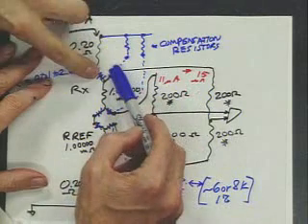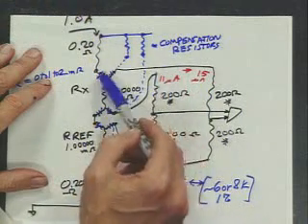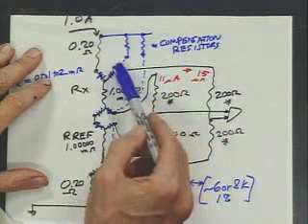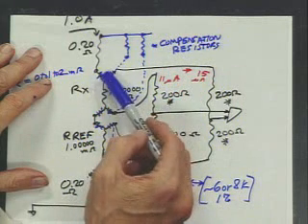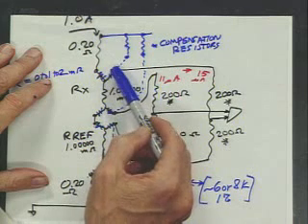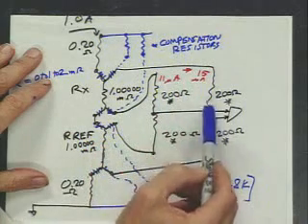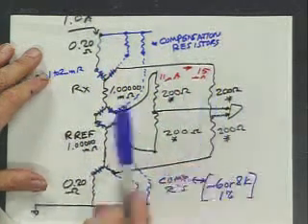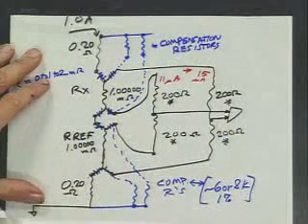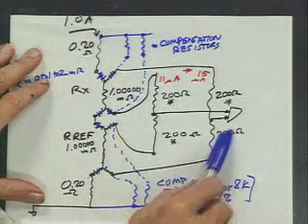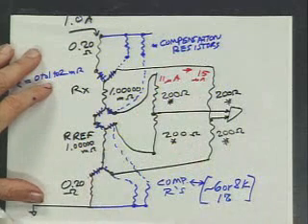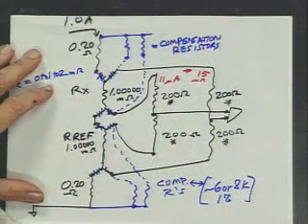We provide the current so the IR drop is nothing, because we don't know or care what this IR drop is; the current is coming past this point in a well-balanced way. Just a few microamps coming down there. And likewise down here, so these currents are all balanced out, and the bridge is substantially perfect.